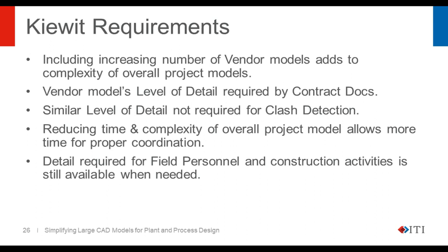And I noticed one of the questions Gary Jones asked about having a separate file with the more details before the analysis goes. We do keep our original vendor models, and we also have an overall detailed model that leaves all that intact, but for our coordination and clash detection purposes, we use the simplified model and keep those as separate entities.